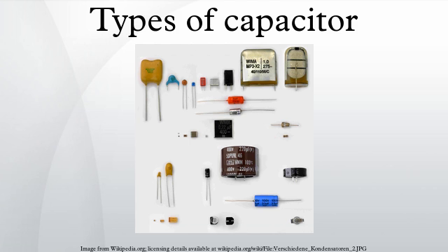The voltage at the terminals generated by the dielectric absorption may in some cases cause problems in the function of an electronic circuit or can be a safety risk to personnel. In order to prevent shocks, most very large capacitors are shipped with shorting wires that need to be removed before they are used.